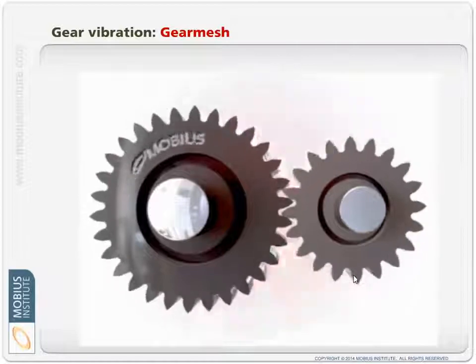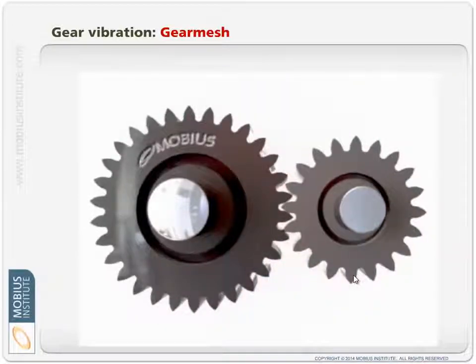That can happen for a variety of reasons, from poor design and assembly of the gearbox, even to VFDs, if there's shuttling of the speed, fast slow fast slow fast slow, then it can cause backlash to occur, and we can detect that in the vibration analysis.